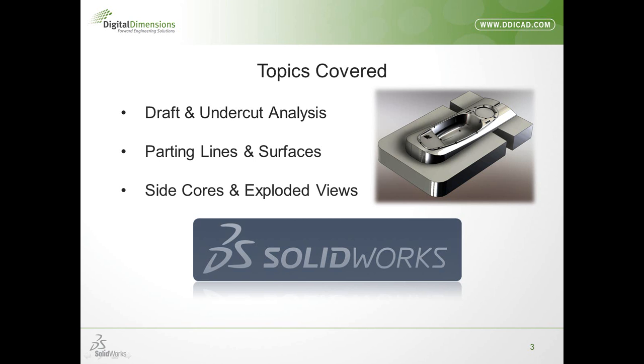Now, mold design is something that's a little bit different than some of the other things that you would do in SOLIDWORKS. Primarily, most of the mold design tools really expect you to be in a single part mode, meaning that while you're creating the mold split, you're not going to be stepping into an assembly mode at the outset. Everything's built off of a solid part, and then from that point you can get your different solid bodies and put that out into an assembly so that you can have different materials and part numbers and all this other stuff that you would need for an assembly. But as far as the creation of the bodies, you're going to get the best result if you do it as a multi-body solid, and that's really the way that the tools expect you to work. So let's go ahead and get going into SOLIDWORKS.